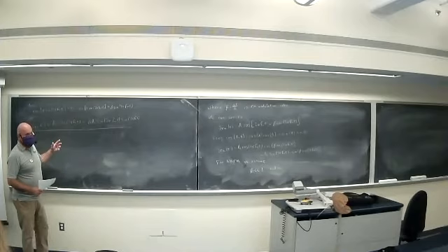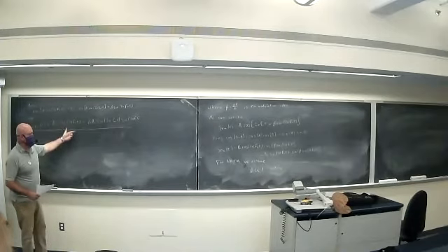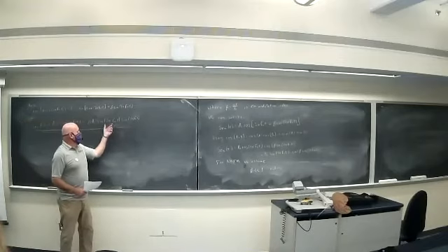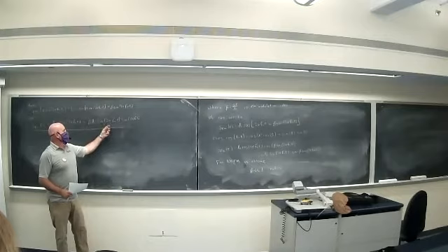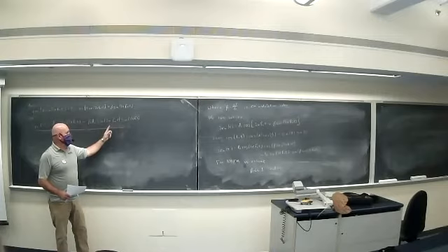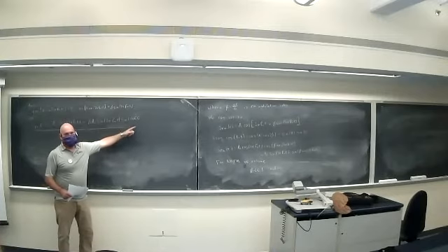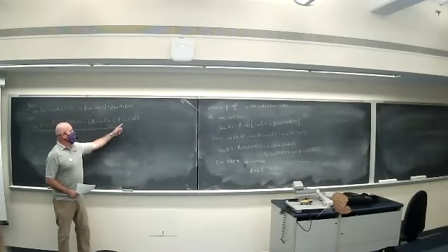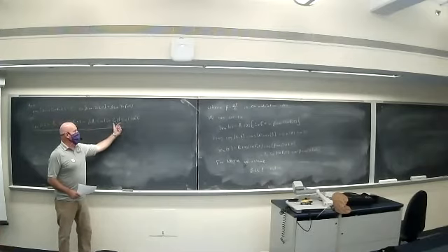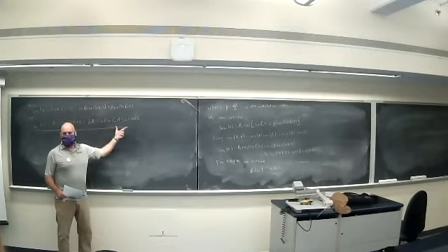I could draw the spectrum here. This is an impulse at fc. This is the spectrum of a tone at our tone frequency, so it'd be a pair of impulses at plus or minus fm, modulated up to fc. Okay. So we got an impulse, and then this is going to produce terms at fc plus fm and fc minus fm. I mean, we've looked at this in the past with 2 cosines, right?